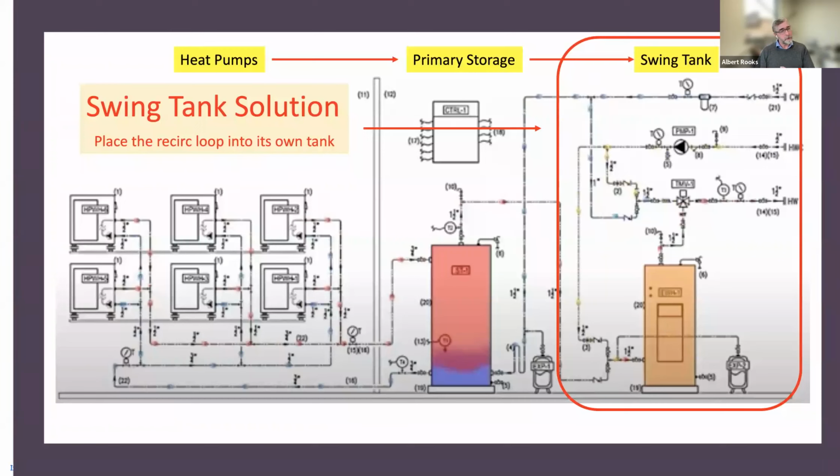And if we've got an electronic mixing valve, it'll very easily accommodate the condition and mix in very little cold water to hit that target delivery temperature. And as it comes back, it brings all those losses back into that one tank. Here's kind of what it looks like.